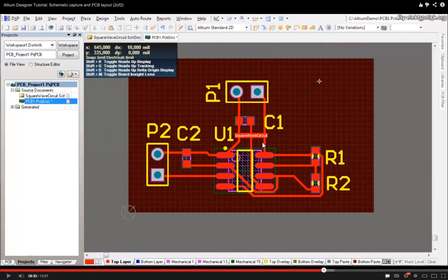so that when you have your PCB, you can actually put it on. So when you can't find a component in the library, don't panic, because you can always make it yourself with the pad, and you can always draw these lines to make sure that you don't mess up the size, so that when you get your PCB, you don't crowd everything. You want to make sure you have enough space between all the components.